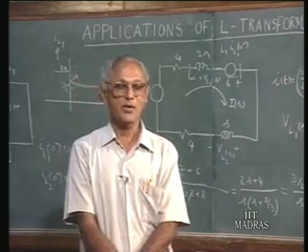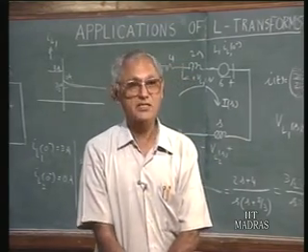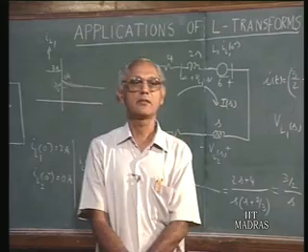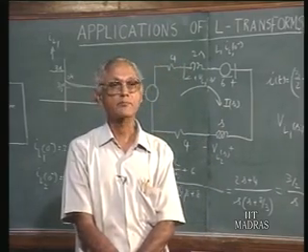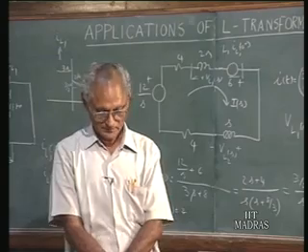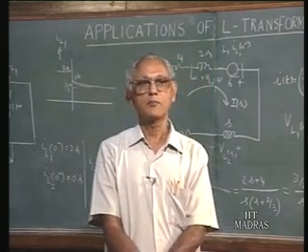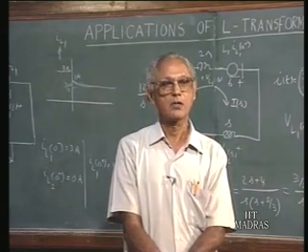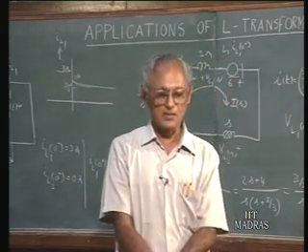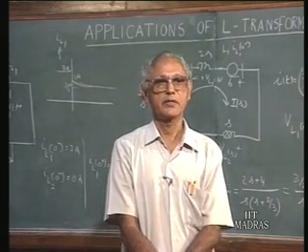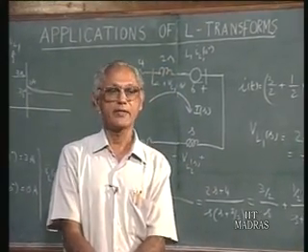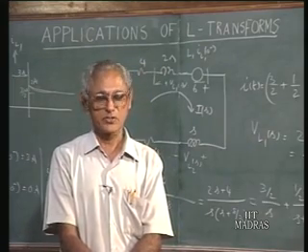To summarize once again, because this is a very important aspect, let me recapitulate the various advantages that we have mentioned. First of all, functions which are discontinuous and which have discontinuous derivatives are easily handled in the transform domain because you get one single expression valid for all time. Secondly, calculus is converted into algebra, so the manipulations are that much easier. Thirdly, the transient and steady state solutions come together in one package, but you can separate them in the final solution into the two separate components if you so wish. And most important of all is the fact that the initial conditions are used in the problem to start with. The data regarding initial conditions is fed into the problem in the very beginning itself, so separate evaluation of arbitrary constants is avoided. This is a troublesome feature as far as the classical differential equation solution is concerned.